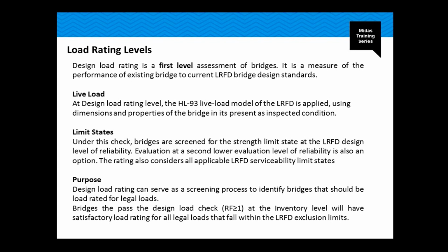In this case, the bridges that pass the design check, which is the design load check, which is the rating factor higher than 1 at the inventory level, we have a satisfactory load rating for all legal loads that fall within the LRFD exclusion limits. So it's basically applying the LRFD standards to the load rating using the HL93.